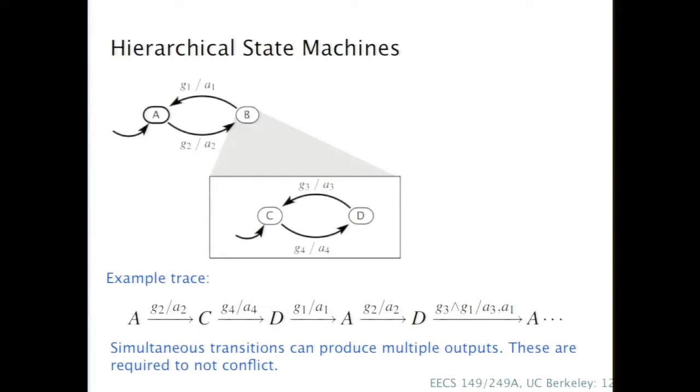But suppose you had a single output port with an int data type, and the transition in the refinement sets the int to 0, and the transition in the higher level state machine sets it to 1. Then what is the output? It's a single reaction, so the output cannot be both 0 and 1. And it can't be a sequence, 0 to 1. It can only have one value in the data type. So again, you need a semantics. And there are several choices. One choice is it's undefined. Your state machine is erroneous.